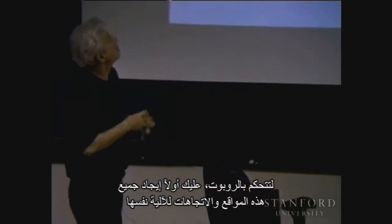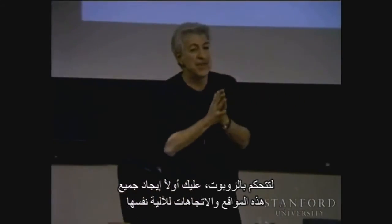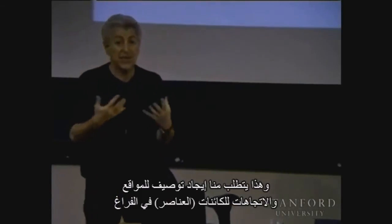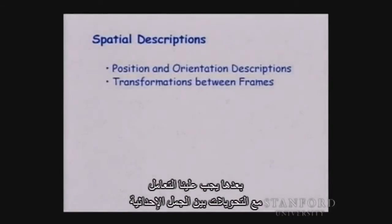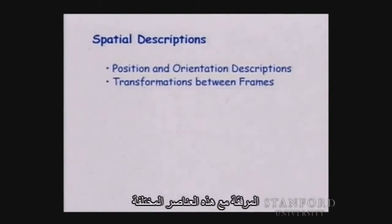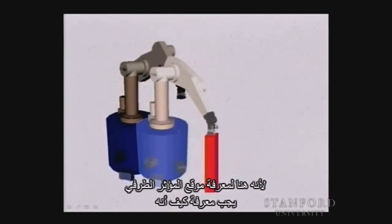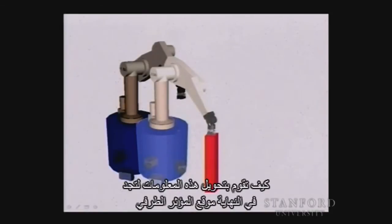So to control the robot, first you need to find the position and orientation of the mechanism itself, and that requires us to find descriptions of position and orientation of objects in space. Then we need to deal with the transformations between frames attached to these different objects, because to know where this end effector is, if you know the position of those different objects, you need to transform those descriptions to find finally the position of your end effector.